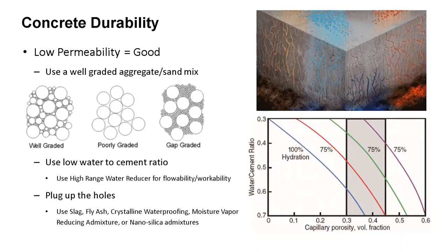So what happens is when we mix water into the mix and we have more free water than the cement is required for hydration, that water has to get out of the concrete. And in getting out of the concrete as it dries and cures, it creates the little paths that you see in that image in the top right. And those are now paths for chemicals, for water, for air to enter the concrete and cause issues in the future. So for good reason, structural engineers are worried about water. And this is why, in large part, because it creates higher permeable concrete.